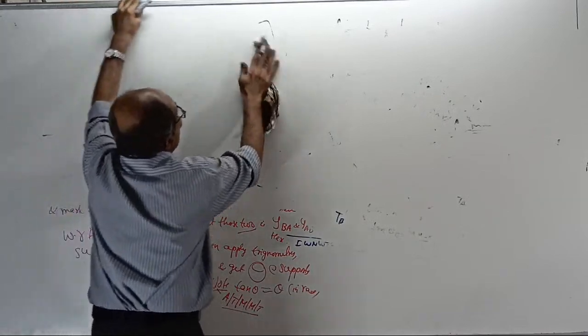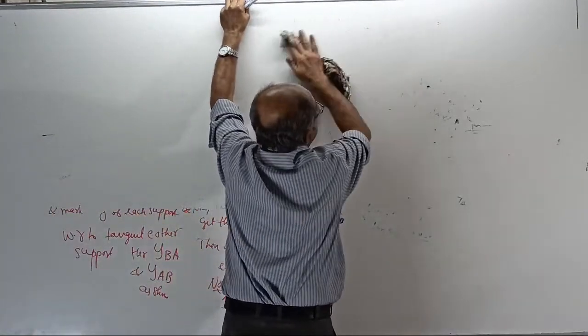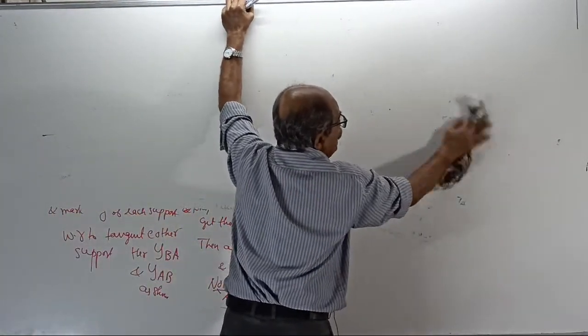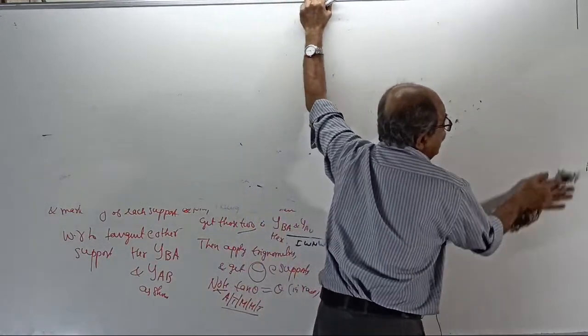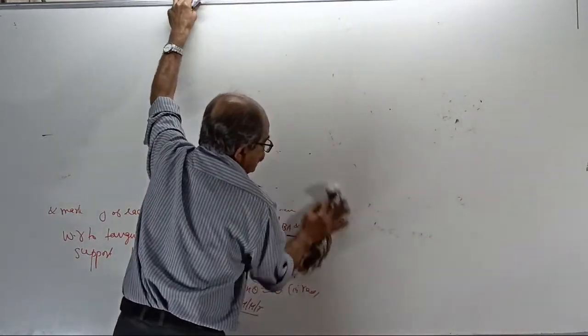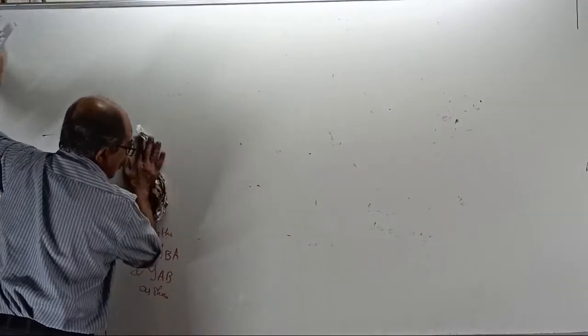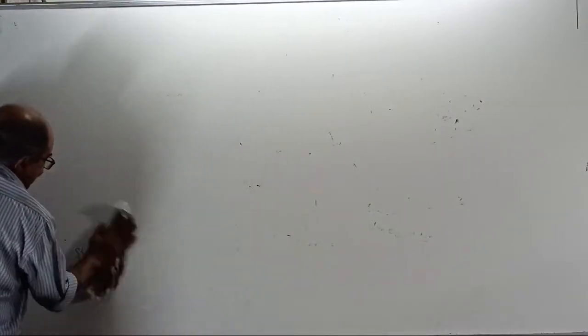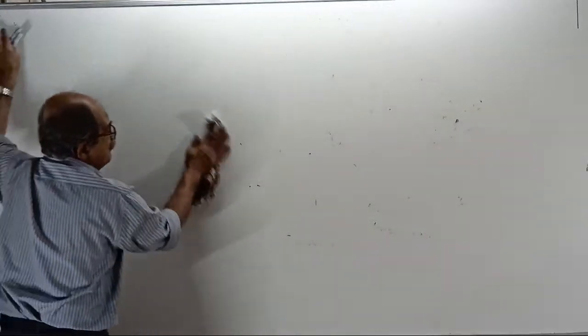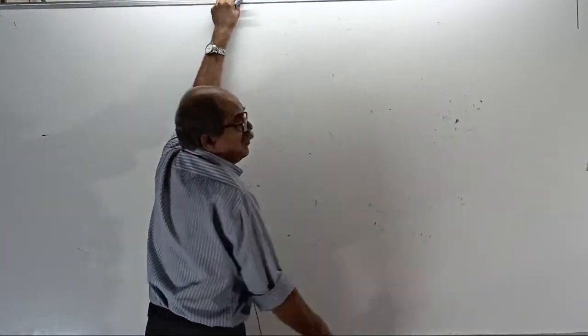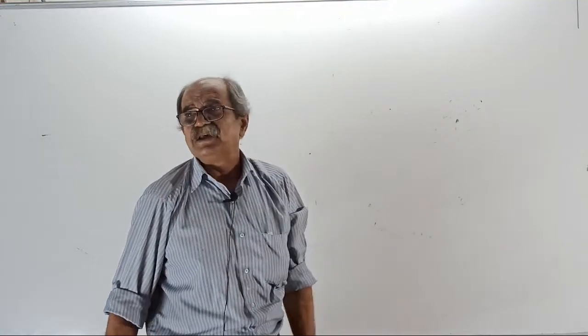And one more note. See, when you draw a bending moment diagram when it was symmetrical, so far you wrote, due to symmetry, VA equal to VB equal to total load by 2. That you cannot write here. You have to take sigma M and sigma V equal to 0 and get the reactions. Okay, start.